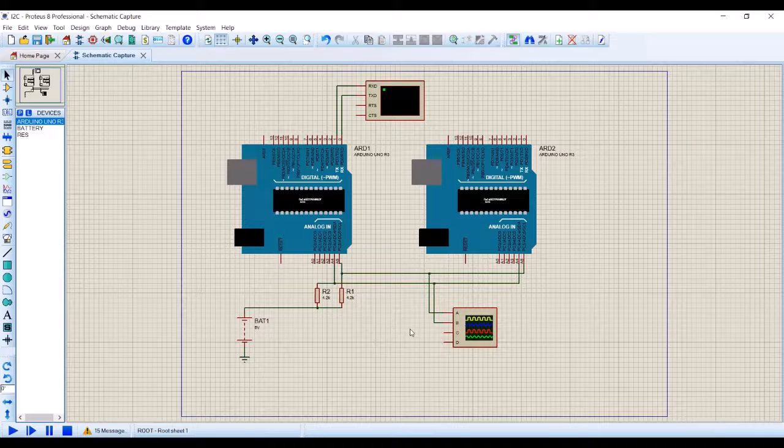So if the address is correct and the slave acknowledged and like that, you can figure out where the problem happens. So that is what you have to do in real life. That is how you debug any system if it doesn't work, right? Otherwise you don't know where to start.